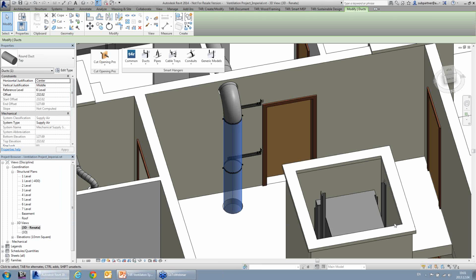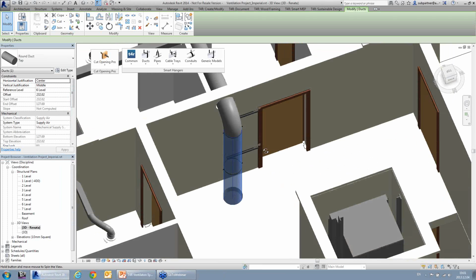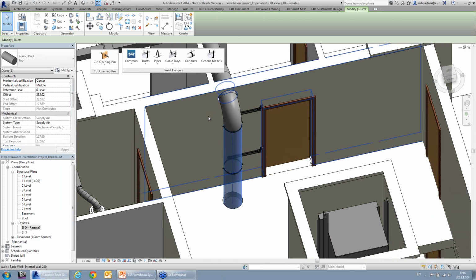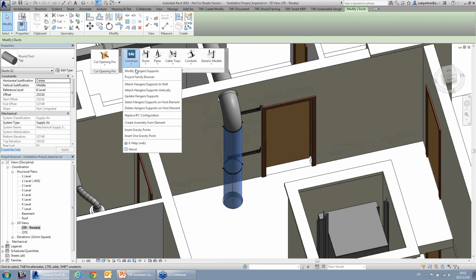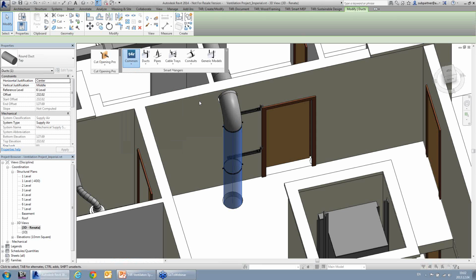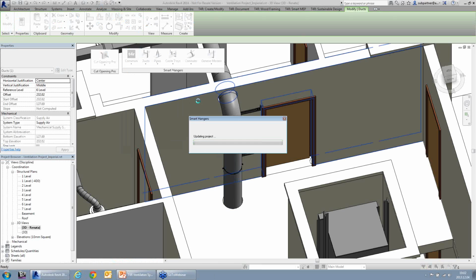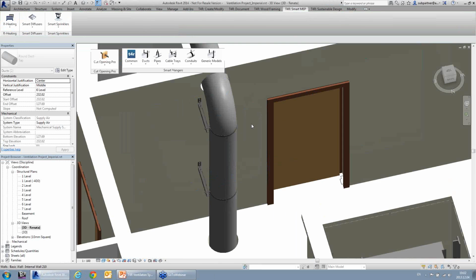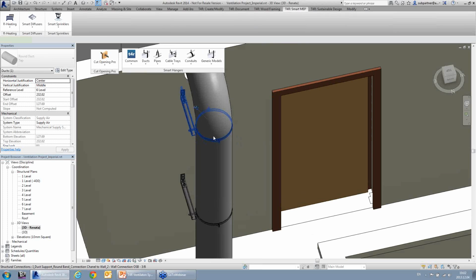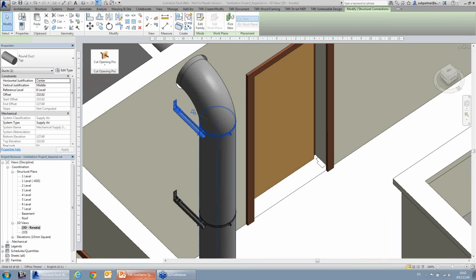There are 3 elements inserted, and as you see, we would need to rotate those supports, and we would need to connect that supports to our selected wall. So here it's very easy to do that. You can just go into the common functionalities, and here we have functionality attach hangers or supports to the wall. Just pick the wall, and the tool automatically will rotate those supports for you.